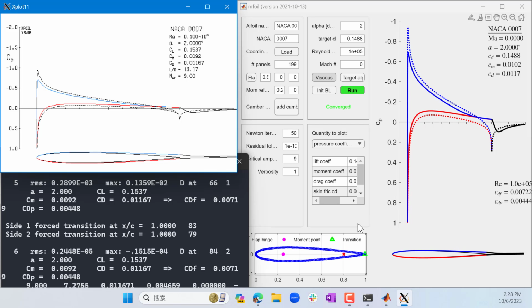But in reality, the angle of attack didn't change, right? It's still 2 degrees. So effectively, it's like the airfoil has pitched down a little bit, or the trailing edge has raised a little bit, right? So even if the flow is going in an upwards direction, but if the airfoil has pitched down at the same time, then the angle of attack relative to the flow is not going to be as high as 2 degrees, right? Okay.